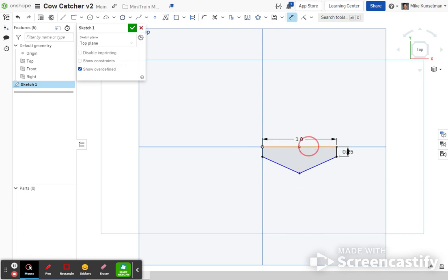On this bottom one, that sticks out an inch. Let's just double check that this is in fact 0.25. Cool, it is. If it's a redundant dimension, it'll gray out, and sure enough, it is. So we do not need that. Let's make sure that this is in fact 0.9. It's in the middle, and cool, it's also redundant, so our little snapping worked perfectly. We don't need these dimensions. So that's where we're going to leave that bottom sketch.